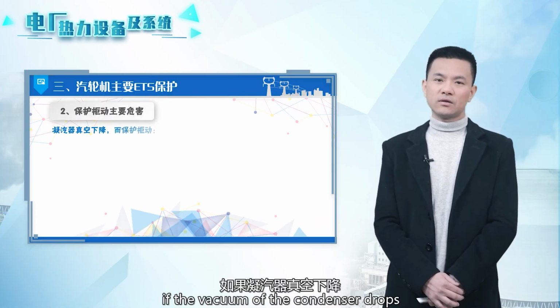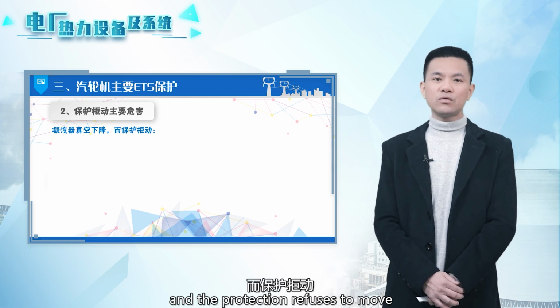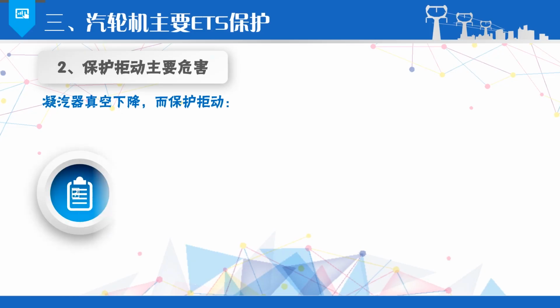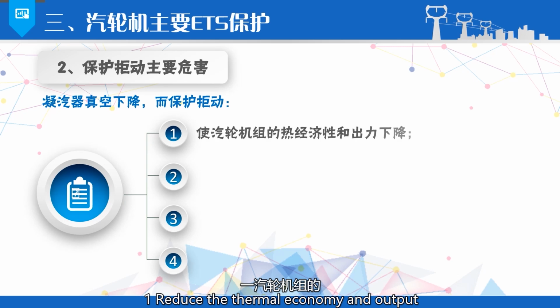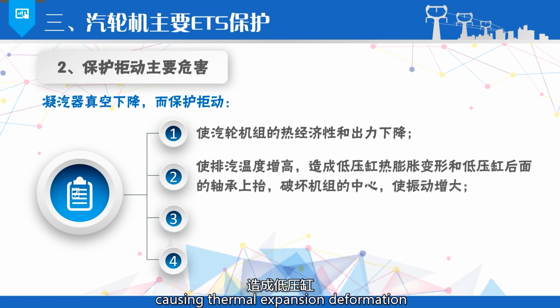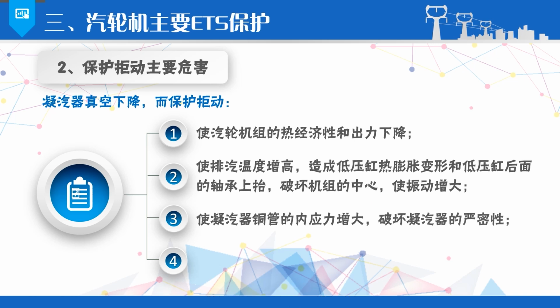For example, if the vacuum of the condenser drops and the protection refuses to act, the consequences are: first, reduced thermal economy and output of the steam turbine unit. Second, raised exhaust temperature, causing thermal expansion and deformation of the low-pressure cylinder, and lifting of the bearings behind the low-pressure cylinder, damaging the center of the unit and increasing vibration.